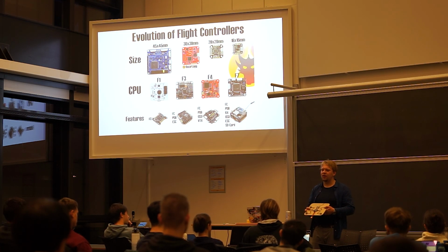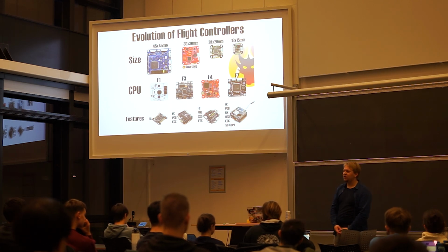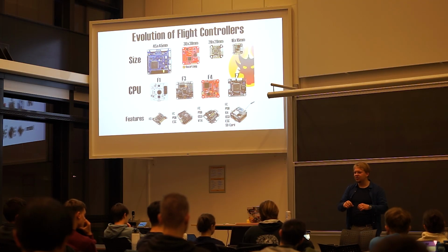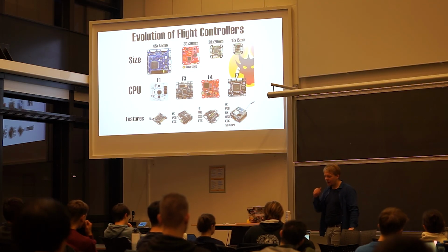You needed another electronic component called the PDB, Power Distribution Board, to connect the ESCs, electronic speed controllers, together. It was just a big plate with a big plus and a big minus. You connected the battery to it, then connected the big pluses and big minuses to those of each ESC. That's how it works.